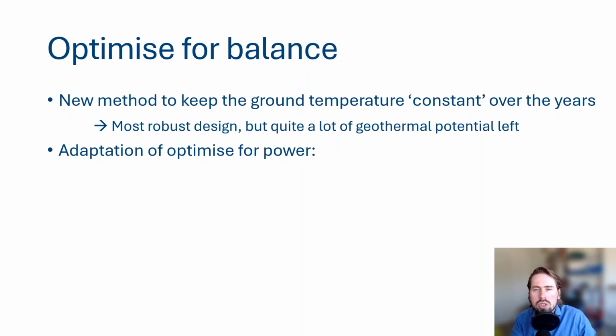And the main advantage of this method is that we have the most robust, the most reliable design, because we know that the efficiency of our heat pump and the temperature of our ground will be the same through every year. So there is no problem when it comes down to our simulation periods. There is no discussion whether it's 20 years or 40 years, because it will be the same.